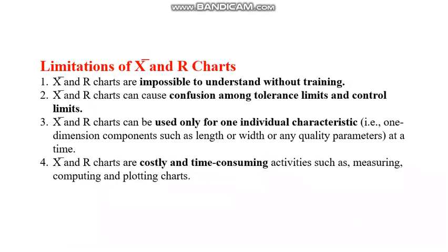So 50.02 mm will be the upper tolerance limit, and the lower tolerance limit will be 49.98 mm. Sometimes there may be confusion unless you read this subject well and understand it properly. There are two limits, and which is this limit and which is that limit.